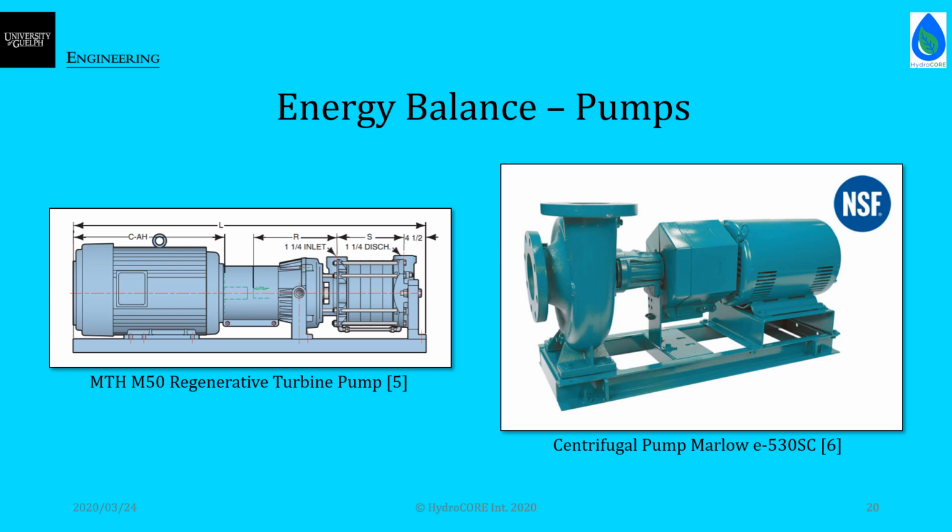In order to operate the treatment and desalination processes with acceptable pressure, 2 pumps were sized. The first of these was a centrifugal pump that is used to collect surface water, and the second was a high-pressure turbine pump that provides the necessary pressure for reverse osmosis.